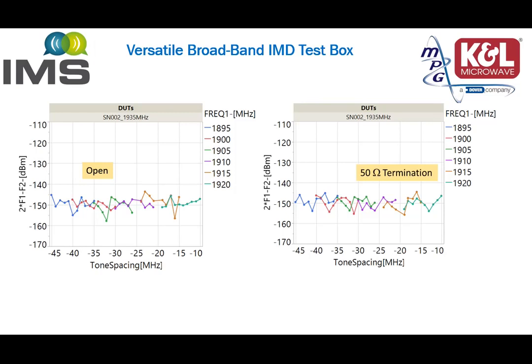Another interesting feature of the bandpass bandstop duplexer is that we can achieve almost no change if the common port is 50 ohm terminated or opened. This suggests that there are no IMD sources within the bandpass bandstop that otherwise, through phasing, might change the amplitude.